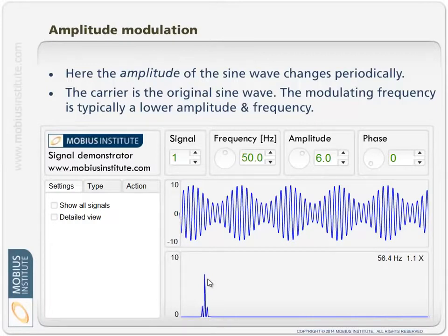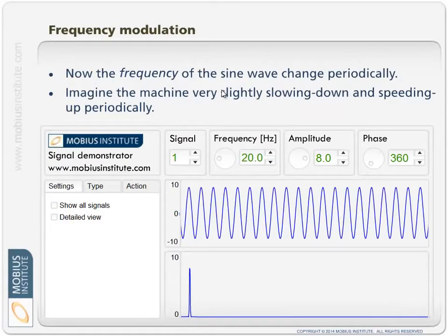So when you look at it, you might see a peak and think, wow, it's not an integer multiple of running speed, I don't know what it is. But you might find that if you subtracted twice line frequency, there might be a small peak in the spectrum, and that would be an integer multiple of running speed. It would be the number of rotor bars. Anyway, we can see various combinations of these sorts of things, which we'll explore a little bit in just a second. So that is amplitude modulation, and shortly I'll just summarize a few things regarding the sidebands.